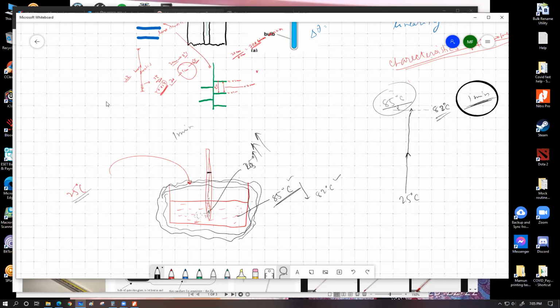That required amount of time might be very small for certain types of thermometers. For example, thermocouple thermometers take a very small time. That required time can be very large for some other thermometers. For example, in this case, for an alcohol thermometer, that required time was 1 minute, but it can vary. Depending upon this varying amount of time that they require to give us a temperature reading is what we define as responsiveness. The thermometers which can give us a reading pretty fast, we call them more responsive. Thermometers which give us a reading pretty slowly, we call them less responsive.